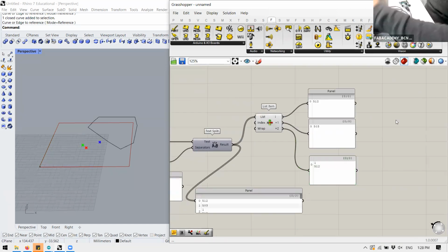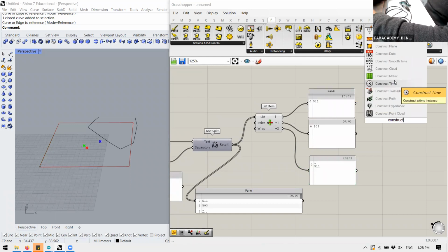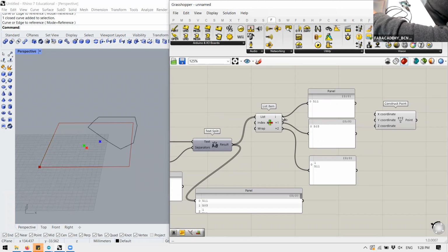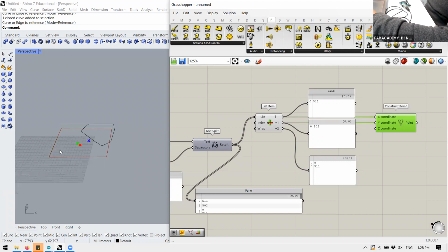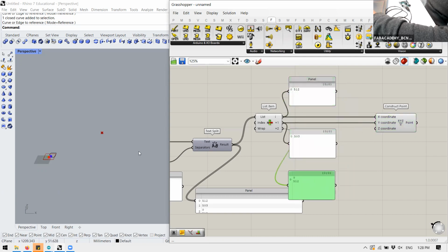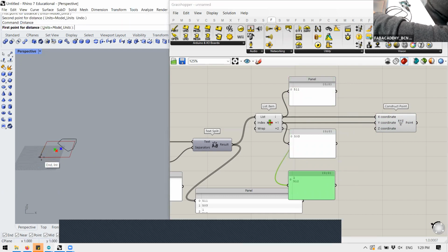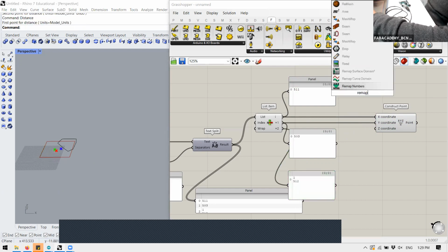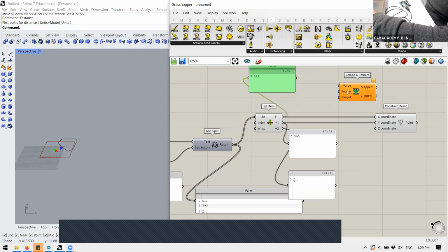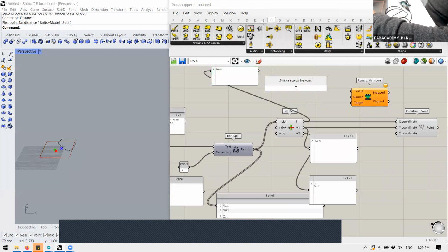Okay, so we have two numbers. What we can do with this, for example, is construct a point. So we have a point. What will be the range of the point? This point right now is too huge, let's say; our workspace is 0 by 100. So what we can do is remap this number. Do we know the source range? 0 to 1,024. Exactly, it's the analog values.